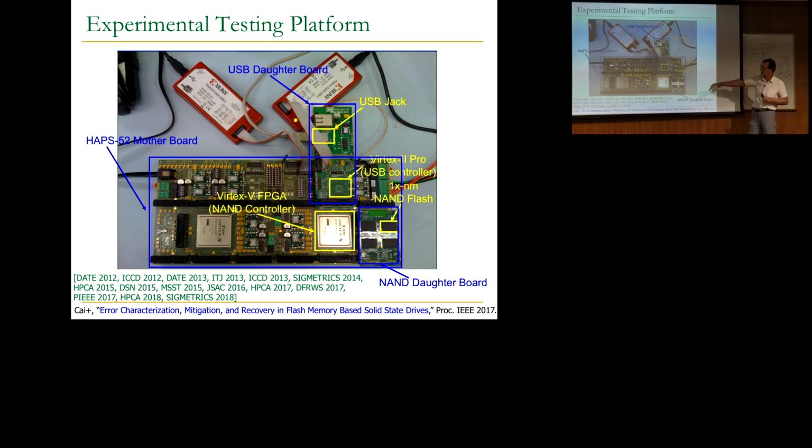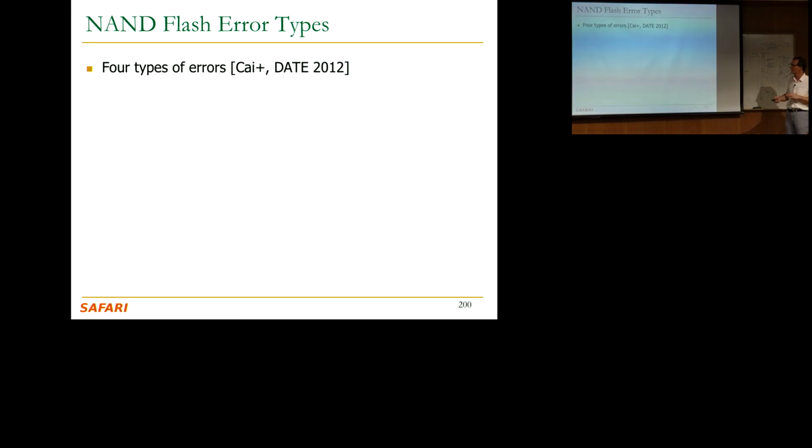At the time, this is about 2011 or so. This is very similar to our DRAM infrastructure. It's a NAND controller with access to some special commands from the flash manufacturers, such that we can actually, in a more fine grain, read the voltages of different cells. I think infrastructure is really important. This took about 1.5 years to build and also calibrate.